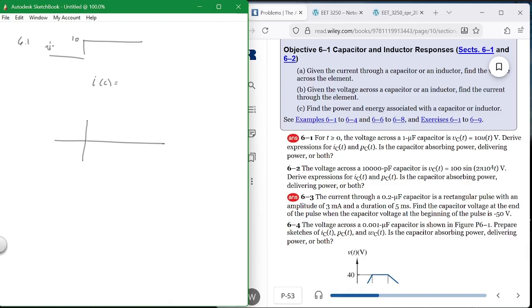This is voltage. What would be current? They don't talk about it, but right at t equals 0, it goes really high in a spike, okay? I equals C dV over dt. But after that, it goes back to 0.